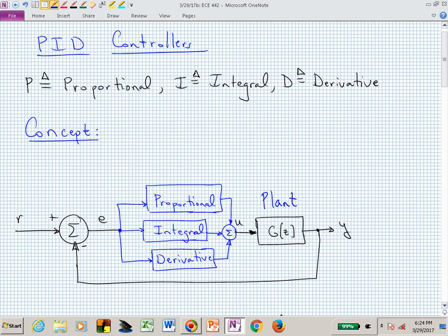Meaning, if I clap, not too fast so that we understand, let's say that's n equals 0. Then we have r of 0 and we have y of 0 at that same instant. And we're assuming that y at that time instant is available instantly at that summing junction. So we have r of 0, y of 0. That creates e of 0. That's our error at time 0.